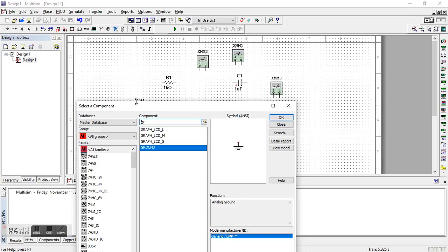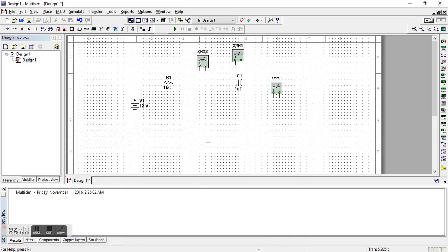Then we connect the wires from the source to the resistor. Then to measure the current, connect the resistor in series with the ammeter. Same with the second ammeter. Then connect back to the source. Then we'll adjust the wires a little so that it will look better.